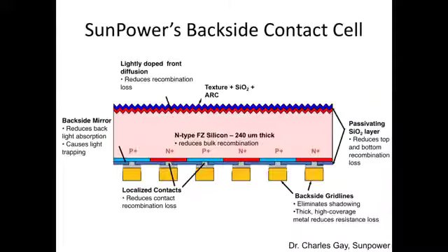These passivating layers are simply layers at interfaces, which are really common places for recombination, so voltage losses in the cell. They use a silicon dioxide layer to passivate these layers. So essentially, clean up dangling bonds, clean up mismatches, essentially efficient transfers of energy between the interfaces.